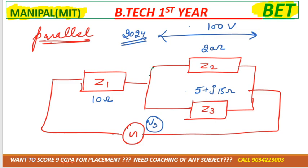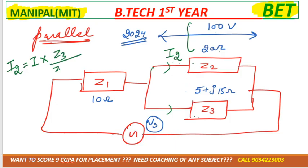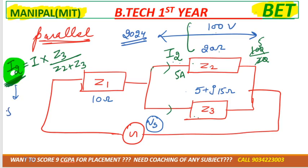So we'll solve this question in the next class. But I'll give you a little hint, try it, and if it doesn't work out, I'll tell you. Voltage is given, resistance is given, then we'll get I2, right? Now I2 is given, and by using the current division rule, as I told you, I2 is equal to I into the opposite impedance. The opposite impedance of I2 is Z3 divided by Z2 plus Z3. So what is the I2 value we have? That is V by R, so 100 by 20. So how much is I2? That is 5 ampere. So the I2 value they have given is 5 ampere.